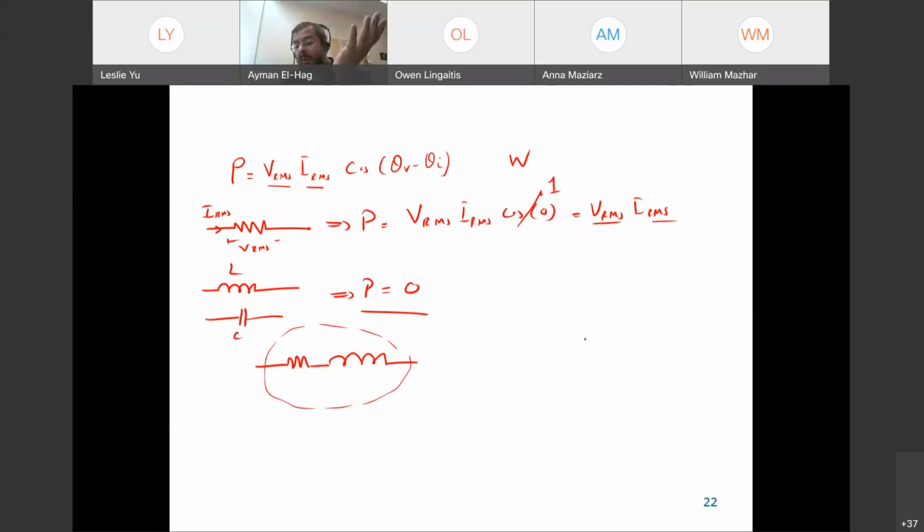And we said that the loads, generally speaking, are either pure resistance, like heaters, or like a washing machine, an inductive load, resistance and inductor. So the resistance is always there. So for every load that we know, there is a consumption of real power. It goes up or goes down depending on the value of R, but real power is consumed in every load.